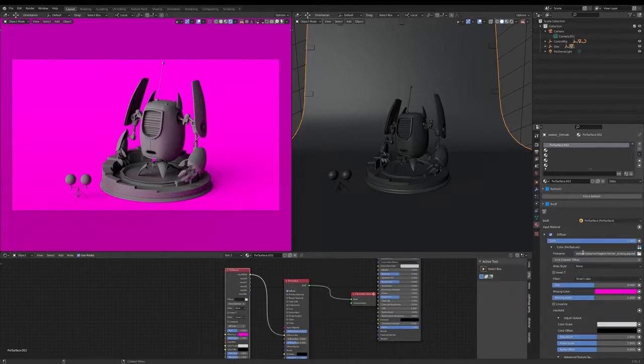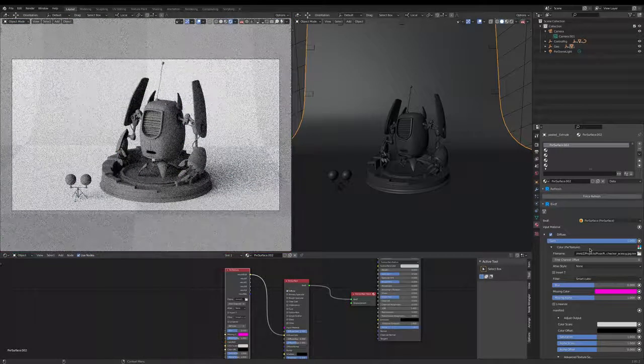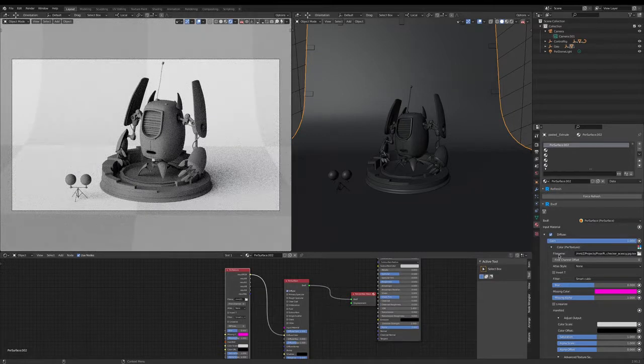So I've already made the texture and I've got a little scene to the left of me on another screen where I'm just cutting and pasting these textures in so we don't have to waste too much time. So I've pasted in this checker ACES CG texture that I've created. Now what I want to do is adjust the tiling on this texture, and I do that with a Pixar manifold 2D node.